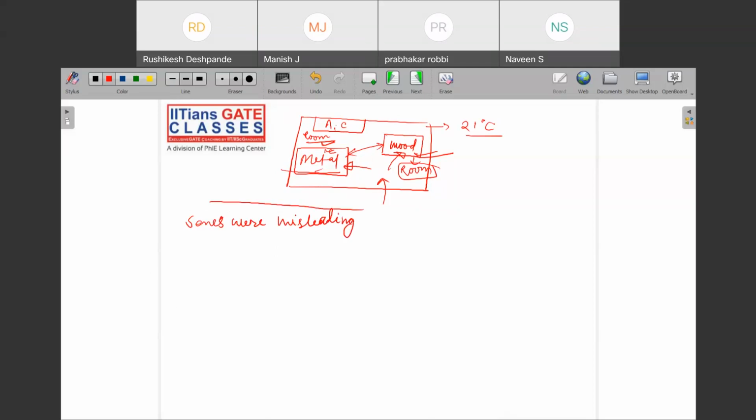That is why this zeroth law was necessary, because if we were checking temperatures by our senses, then our senses were wrong here, absolutely wrong. Why? Because if this whole room is at 21 degrees Celsius, and I told you that it has attained a uniform temperature throughout the room, then it must be that the metal and wood are both at the same temperature. Then how can it happen that my senses tell me the metallic one is colder and the one made of wood has a higher temperature? The only thing is that my senses are not working properly here.